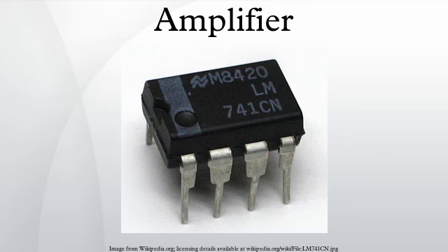Automatic gain control circuits require an amplifier's gain be controlled by the time average amplitude so that the output amplitude varies little when weak stations are being received. The nonlinearities are assumed to be arranged so the relatively small signal amplitude suffers from little distortion yet is still modulated by the relatively large gain control DC voltage.